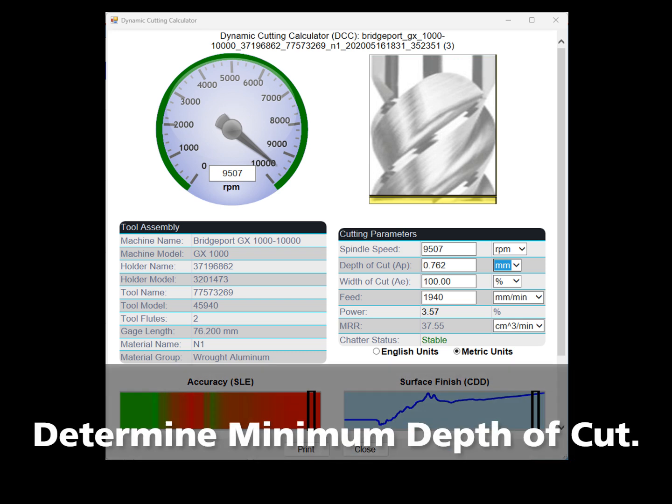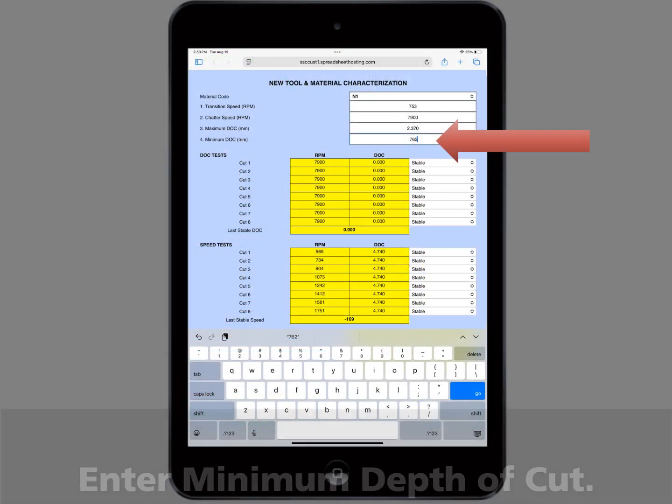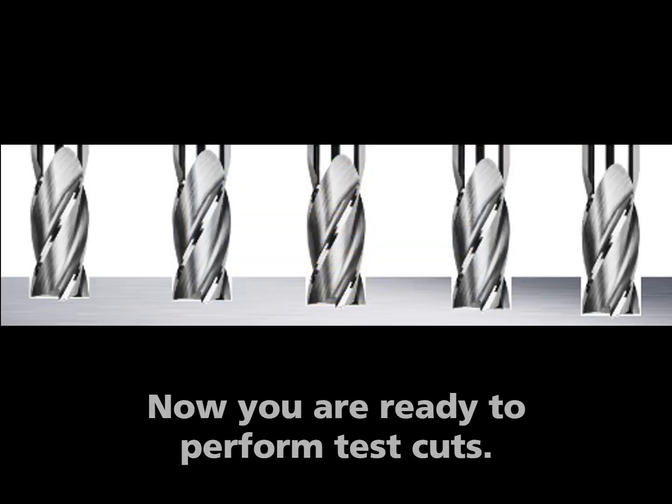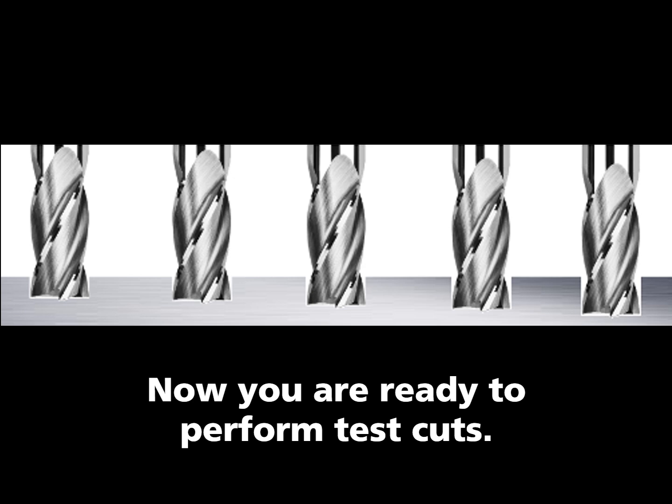Maintaining 100% width of cut, lower the axial depth of cut until the entire dial turns green. In this case, it is 0.03. Enter that depth of cut into the calculator under number 4, minimum depth of cut. Now you are ready to perform cutting tests.